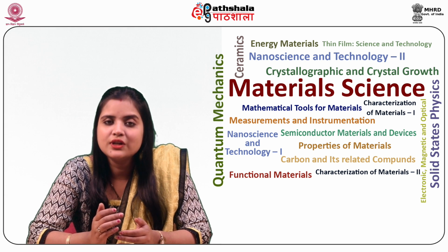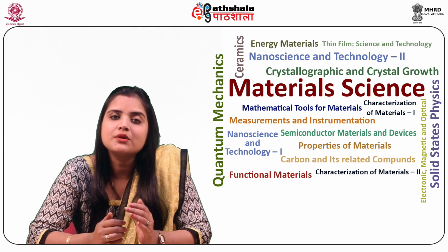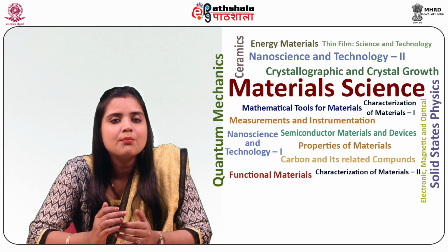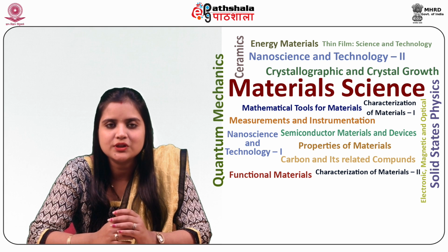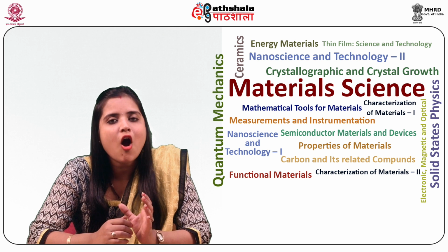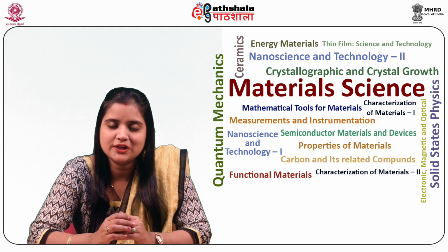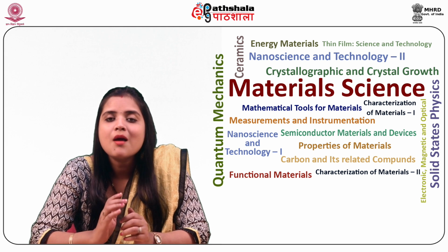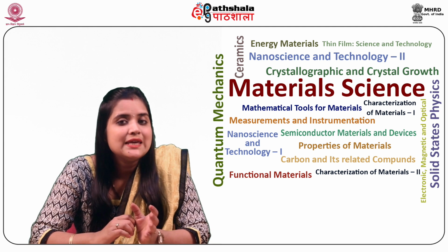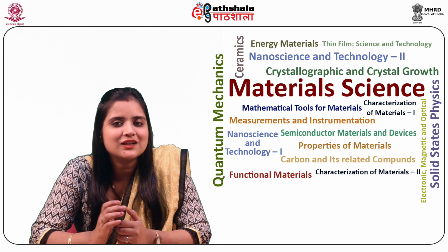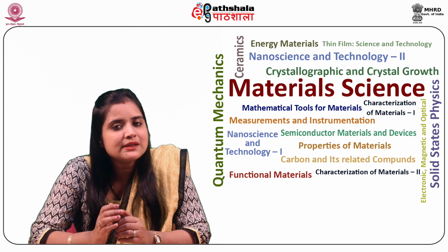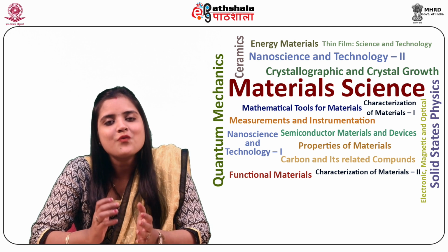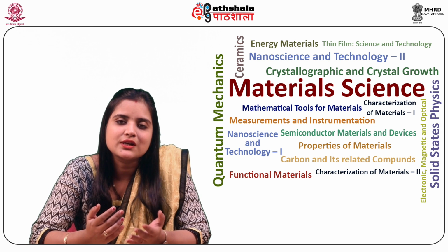Magnetic anisotropy is recognized as the directional dependence of the magnetic properties in a magnetic material. It is considered as one of the most crucial parameters of ferromagnetic materials. It decides the extent of magnetization that can be achieved in a material. Basically, single crystal ferromagnetic materials possess directional magnetization properties, that is, easy and hard directions of magnetization. This is attributed to the energy which is needed to magnetize a material in the direction of an externally applied field with respect to the crystal axis.